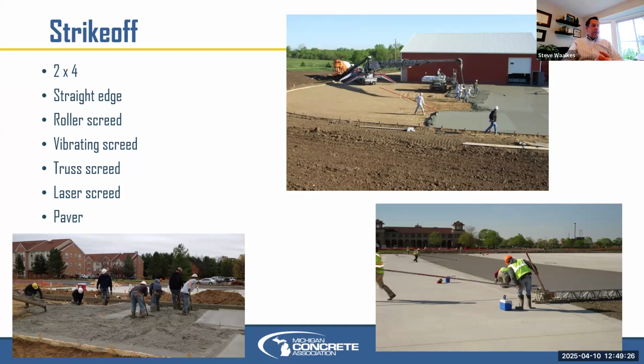You could use a roller screed, or a vibrating screed, pictured bottom right here, sometimes called a truss screed. There are also vibrating screeds that are not truss screeds, like you see being used bottom left here. One of the brands is called a Copperhead, I believe, but it requires the workers to be in rubber boots because they're walking in the concrete as they're backing up to strike off.